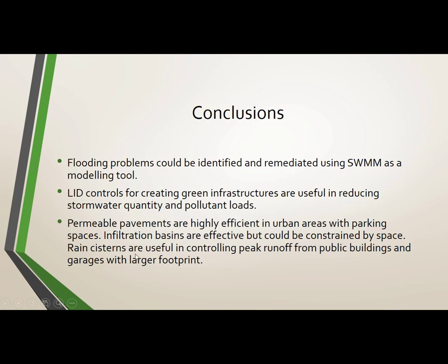And the final point to note in this presentation is that we are not using any rain gardens or other bioretention cells because of the space constraint. Also, for roof gardens it's costly to maintain them for the rest of the year in this arid climate, because we get around 10 days of rainfall, and it's a lot of cost to keep them maintained for the rest of the time.